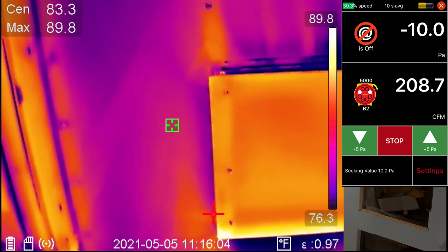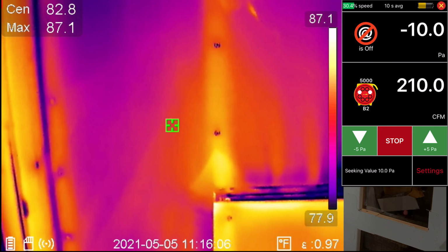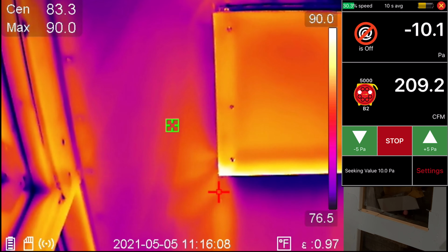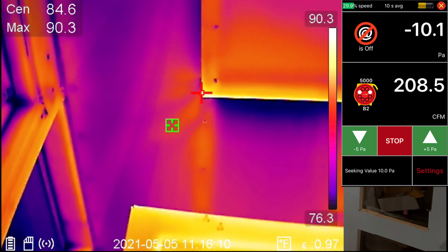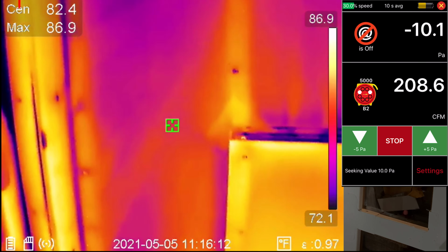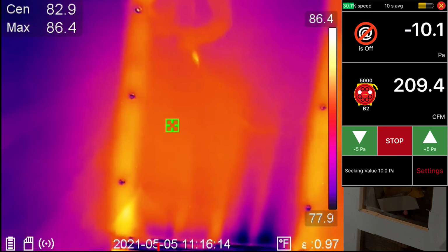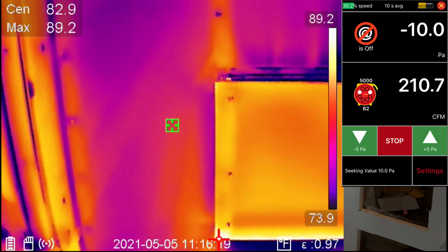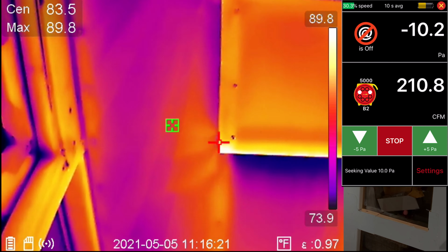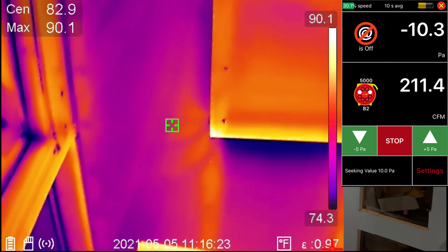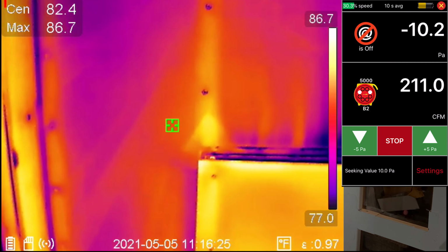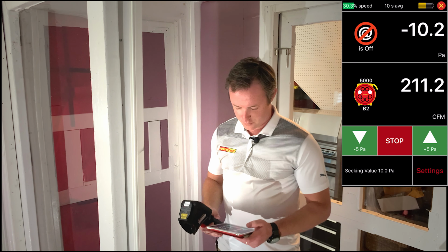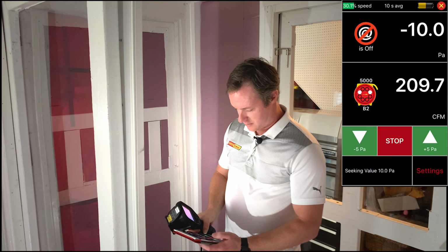And then these other kind of blue purple tones that are starting to show up. Again, that's just going to be some thermal bridging there, where that outdoor air is just coming into contact with that ceiling plate, since there's no insulation there to slow down that thermal bridging. Now we'll bump things up to 25 pascals,